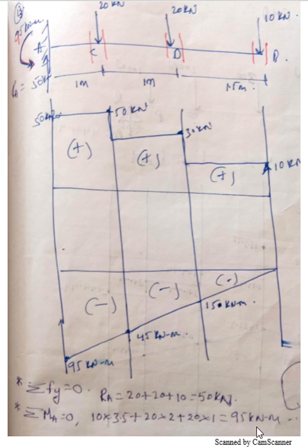This 95 kilonewton meter is the summation of moment because of these forces. So it is nothing but applied moment. I'm getting it as plus 95 in the sense because of applied forces I'm getting clockwise moment, but the reaction force will be equal but in opposite direction. So here it will be anti-clockwise direction and the value will be 95 kilonewton meter. If you are coming from this end, no need of calculating the moment. Okay, we can just skip it.